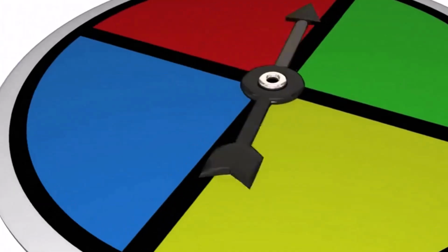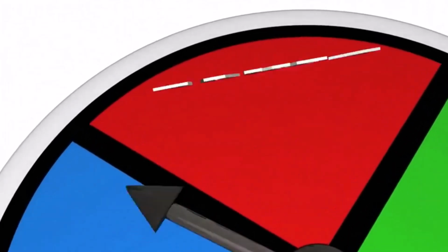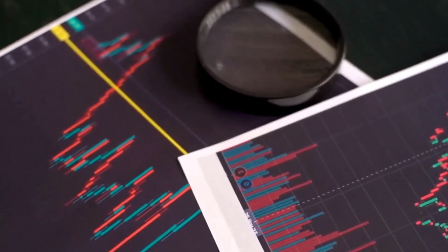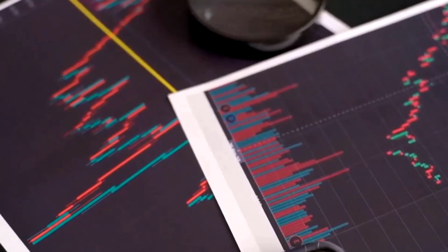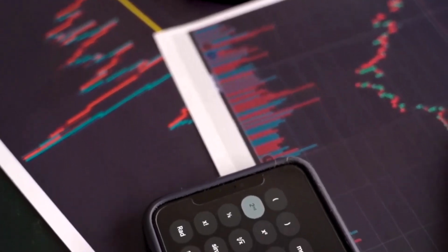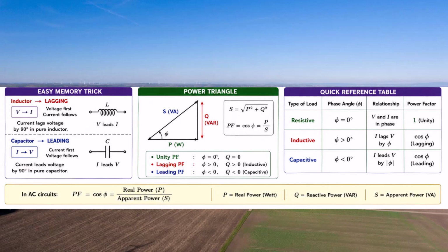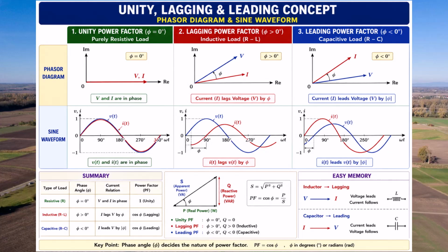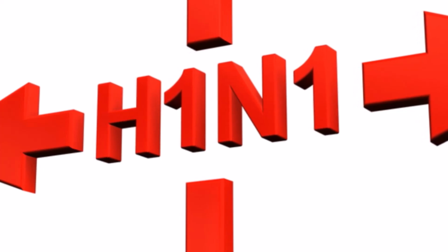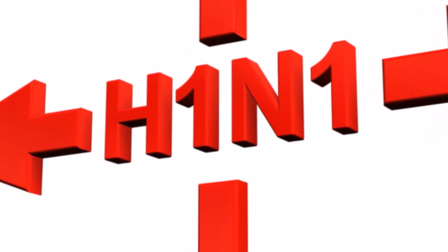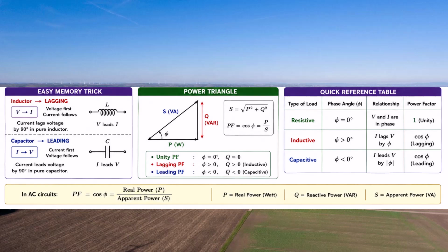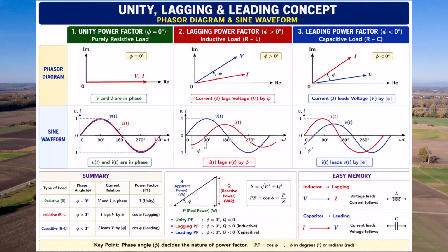So, a phasor is like a snapshot of a spinning arrow that represents a wave. The arrow's length is the wave's peak value, its amplitude, and its angle is the wave's starting point, its phase. Instead of dealing with tricky wave equations, we can now work with these simple arrows. This turns difficult problems about waves into much easier problems about geometry. Adding, subtracting, and comparing waves becomes as simple as figuring out what happens when you put arrows together tip to tail. This visual trick is the first big step to mastering AC circuits.